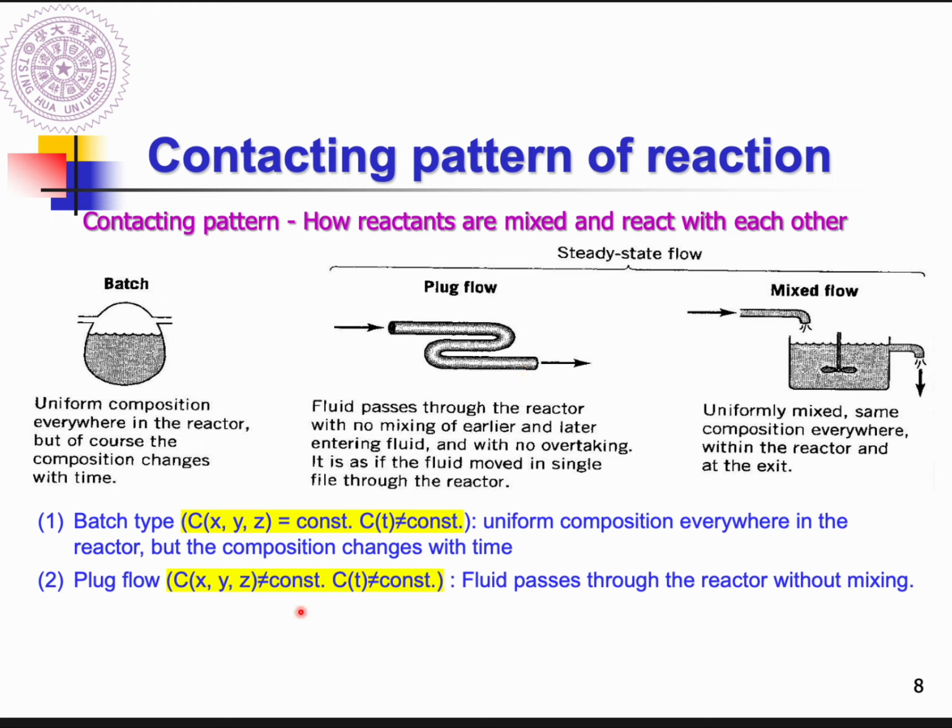Okay, and the third one we call the mixed flow case. They also have a stir bar, a mixer here, to make sure the concentration is the same everywhere. And it is a little bit different from the batch type. In the batch type we put the reactants in at the beginning, but here we always refill our reactants to maintain the concentration of reactants.